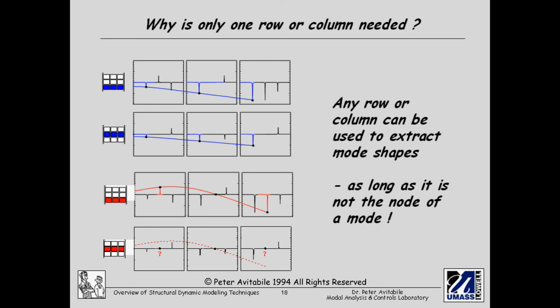Now what I'd like to do is proceed on and look at mode 2. Now if I looked at the lower two sets of plots in red, I'd notice that when the accelerometer is located at point 3, if I measured H31, H32, H33, and I looked at those peak amplitudes, I'd see that the displacement pattern looks like a second bending mode. Now that's when the reference accelerometer is at point 3.